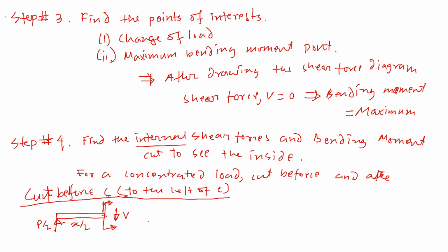So to balance that, the clockwise moment was created by applying this V, and then to apply an anti-clockwise, same amount of moment at that point will actually balance that. Because we cut to the left, I would like to use that L, V_L, and this one is M_L at point C, like that. Now we can easily find the reaction, the shear force at that point.